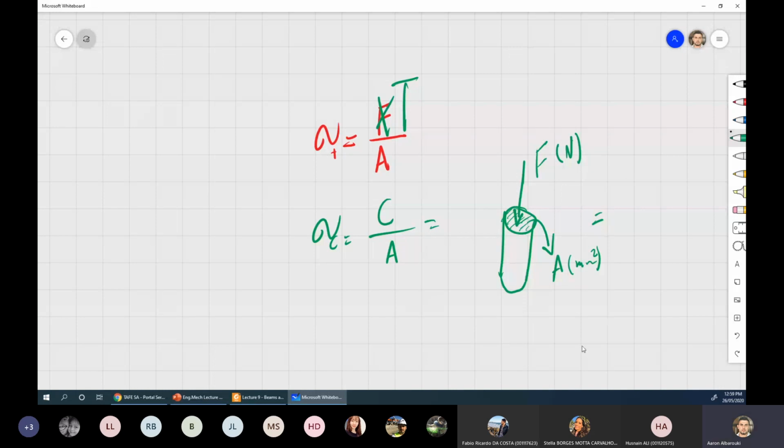divided by the area. So it depends what cylinder they use for testing. Usually we go by 100 millimeter or 150 millimeter diameter cylinder. We compress it by a certain force, and if they got to 32, that's Newton per millimeter square, MPa.